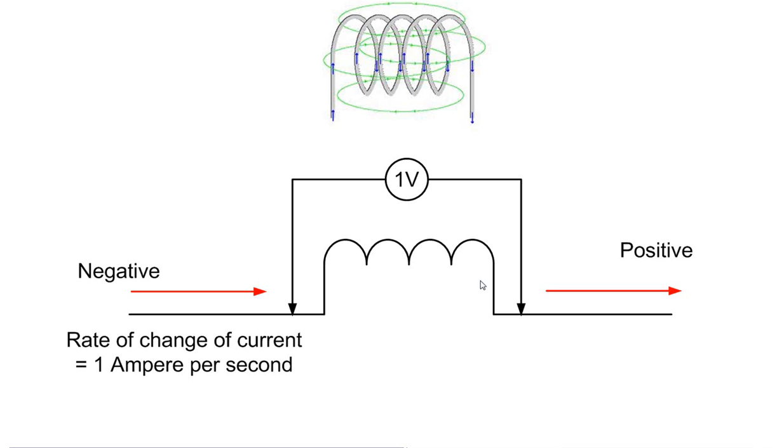If we try to increase current, yes, we can increase it, but it will take a little while before it happens because the inductance will absorb energy. If we try to decrease the current, yes, we can, but it'll take a while to decrease the current because as we're trying to decrease it, energy is coming out of the magnetic field and into the circuit to maintain the status quo of the current.